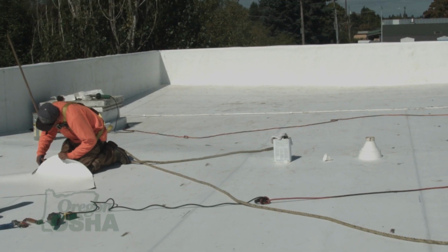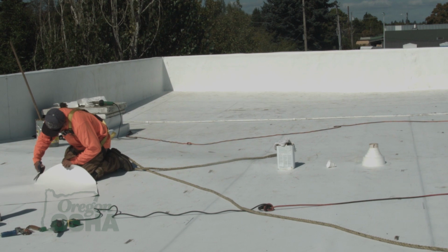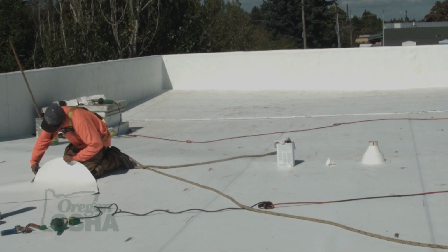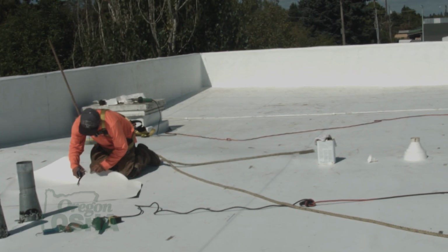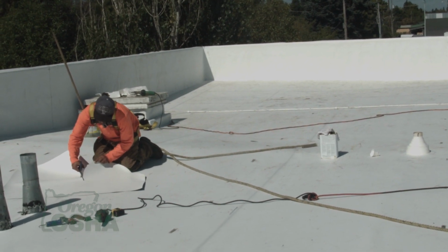We see counterweighted anchors that are brought up to the roof. There are also mobile anchors that I've seen that can go on the roof and provide anchor points for traditional fall arrest systems. I've seen a lot of fall restraint systems being used in commercial low slope roofing as well. So there are a lot of different things that I see our commercial low slope roofers using, and a lot of people are doing that fairly well.